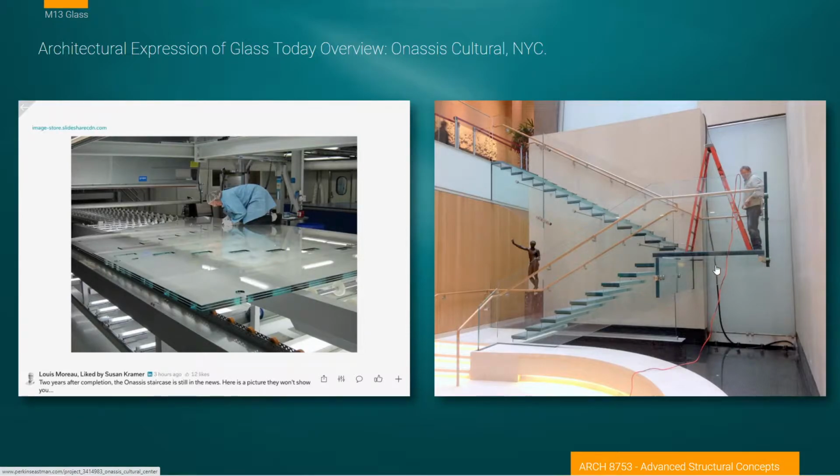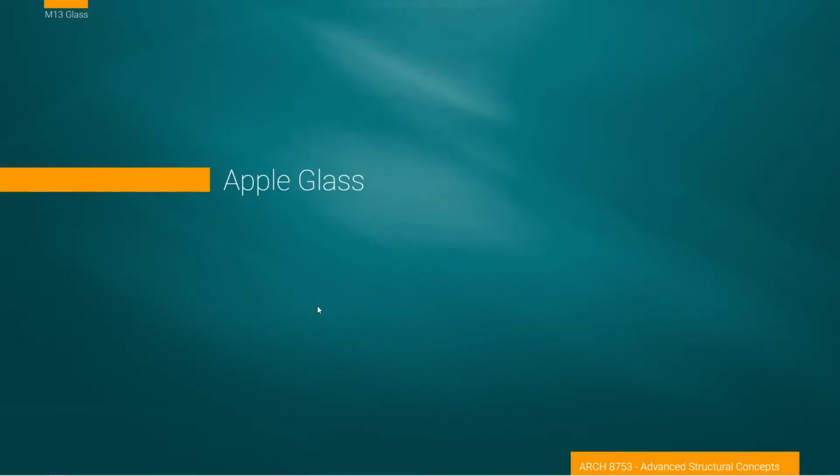Here you can imagine this cantilevered out over what looks like a very lightweight or fragile glass system. You can see what supports it here. You can see this transverse element here. This is a beam coming out, cantilevered from the wall, that's supporting the front part of that deck and the two ends of the stairway. Then the back side is supported by the edges or the side walls of the stairway. But we have a very rigid structural system that's also transparent. And these are hyperlinked to a presentation.